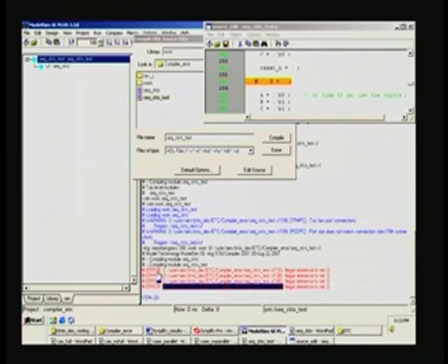So, the error gives the path name of the file, and it gives the line number here, and this is some 153 line number, and that is precisely what it is here in the open file. And it is reporting there because D has been referenced, it has been forced to 1 here in the test bench, and because it is illegally declared as wire instead of reg, so it is promptly reporting. And what it says, after the line number, is illegal reference to net, then colon D. D is the signal in question.